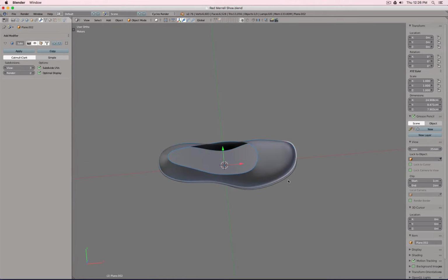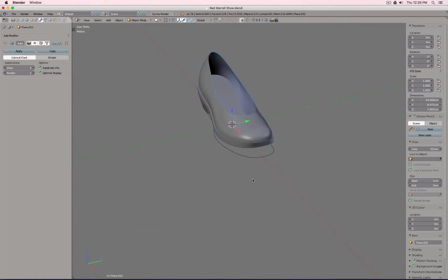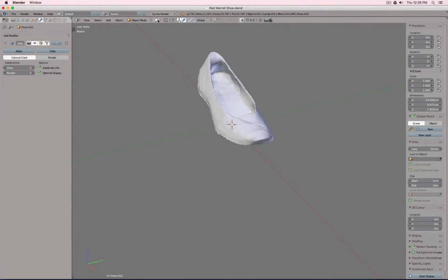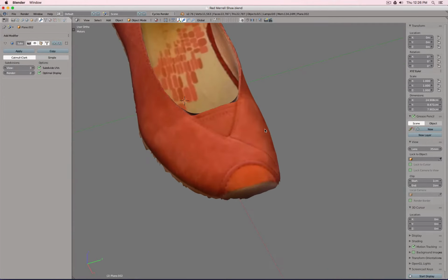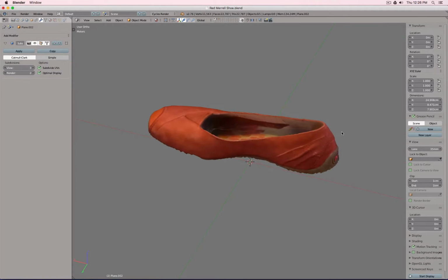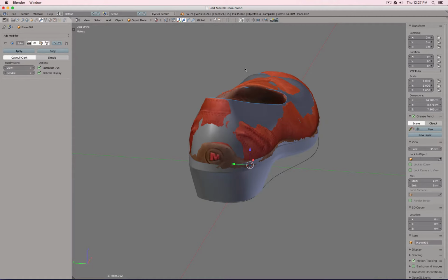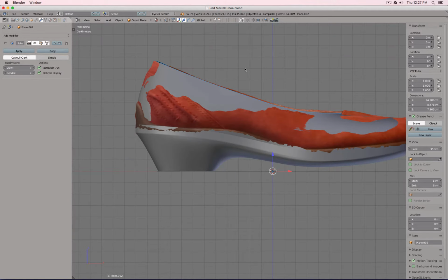So this is not too bad. Let's assume this is correct. Now the question is, well, how do we continue? How do we get the other fabric details on? So with other details, for example, maybe this stitch part and for example this back area. As you can see, this piece has its edge here, so this area is this part. So that's actually not very difficult to do, and there we can make use of our shrink wrap modifier.